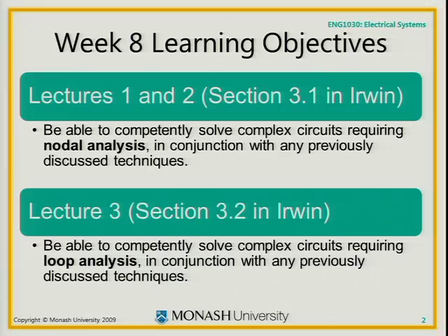But if I gave you a much more complicated circuit and said, find these voltages and currents, you might think, I can't guarantee that I can do that. It might require some inspiration. But it doesn't. And that's what we'll see this week. If you systematically apply Kirchhoff's current law at every node of the circuit, you can solve for everything. If you systematically apply Kirchhoff's voltage law around loops in the circuit, you can solve for everything. And it's a technique that is very, very methodical. You can, in fact, get a computer to solve circuits in this way.